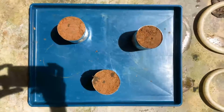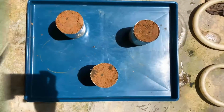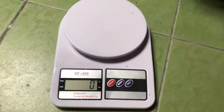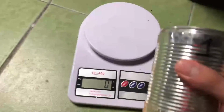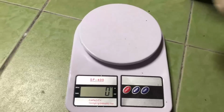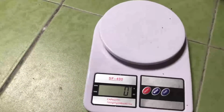After that, we need to repeat the same procedure for the other steel containers and let the soil be exposed to the sun to let the drying process happen. Now we have to let it be exposed to the sun for about 1 day to let it dry. And after 24 hours of drying, now I am going to weigh the steel container again. First container, second container, the third container.